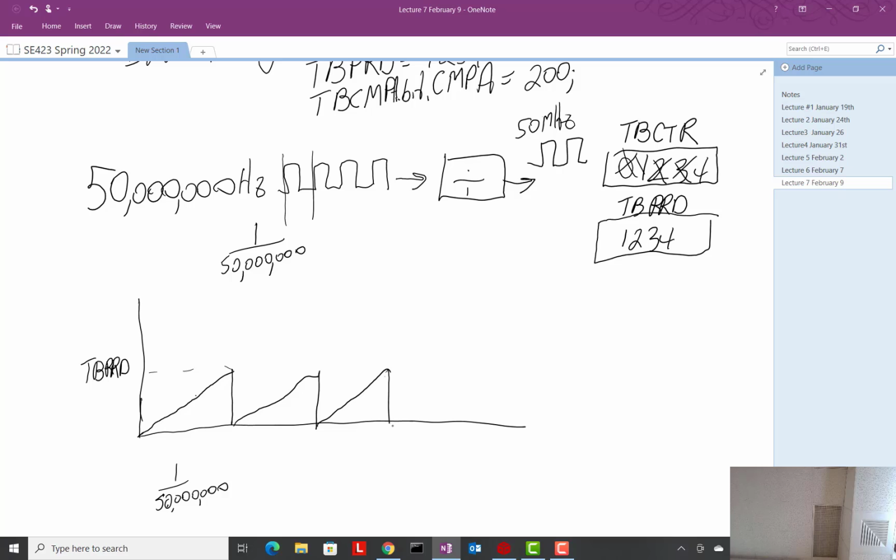If we wanted a 25% duty cycle, we could turn the LED on the first time we come into that interrupt, and then keep it off the next 3 times, making a count. Then the 4th time, we turn it on again, and then 3 times off. That would make a 25% duty cycle, wouldn't it? But that's taking a lot of processor time, checking those counts or whatever to create the duty cycles and all this great stuff.